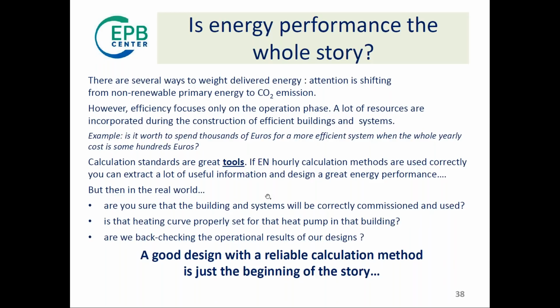It's not just a question of compliance. It's also a question of doing the work and having useful information also for the design. So if the EN hourly calculation methods are used correctly, you can extract a big amount of useful information. But then, of course, in the real world, be sure that building and system are correctly commissioned and used. And an example is a heating curve for the heat pump in that building. And do always some back check of operational results of your designs. And so use the measured energy performance tools of the EN standards to compare and to gain experience.